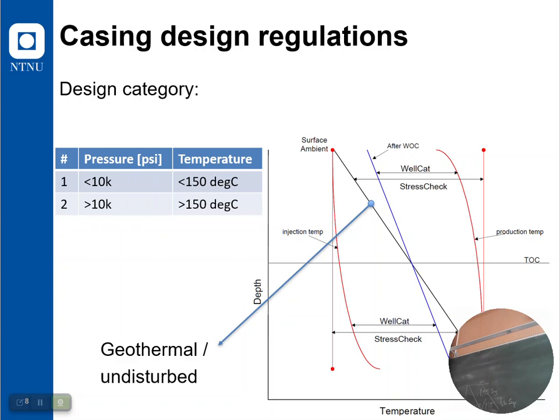So in the top you now have a temperature increase of 50 to 100 degrees. You have heated up your steel, your whole well, with 50 to 100 degrees Celsius, right? It means that the steel in your casing, fixed at the top, fixed at the bottom, trying to expand, it cannot. What does it do? It leaves a stress inside, an additional thermal stress.